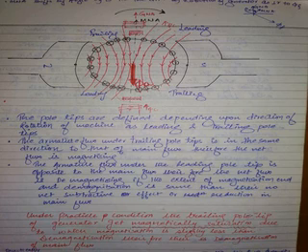And the next pole tip is known as trailing. The naming depends on the direction of rotation of the machine. Since it is rotating clockwise, you have named leading, trailing for the south pole, leading, trailing for this north pole. If the machine rotates anti-clockwise, what will be the naming of the pole tip? If the machine rotates anti-clockwise, this becomes leading, this becomes trailing. So I'm fixing a standard. I'll follow the same thing throughout the entire machines. So the first diagram and this diagram are the same.